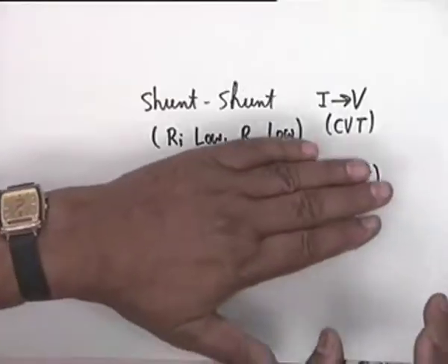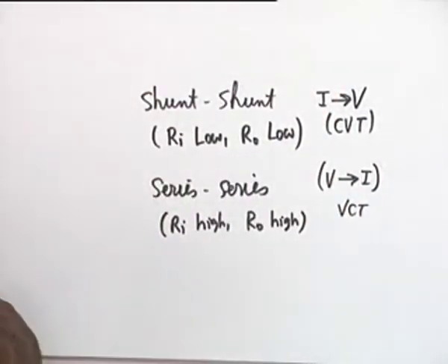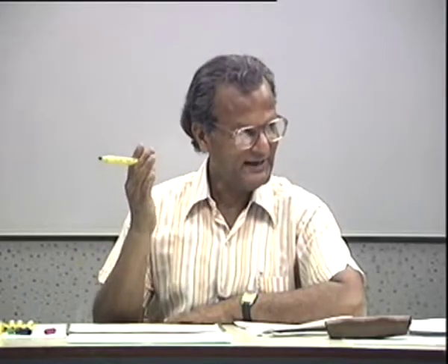Suppose you want to increase the gain. You have designed these two blocks, but individually they are not adequate as far as gain is concerned. Okay, what would you do to increase the gain? Of course, if you cascade two stages, the high frequency 3 dB cutoff is also going to increase or decrease? Decrease. There is always a shrinkage. Whenever you cascade, the bandwidth always shrinks.